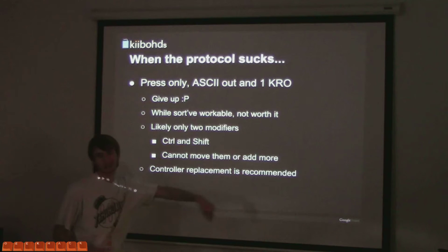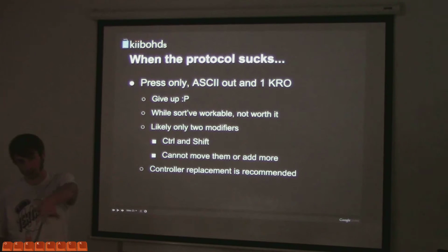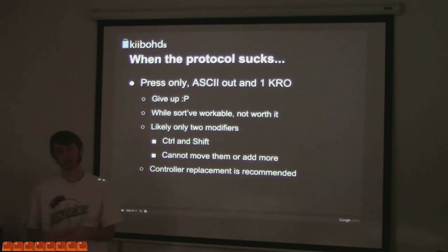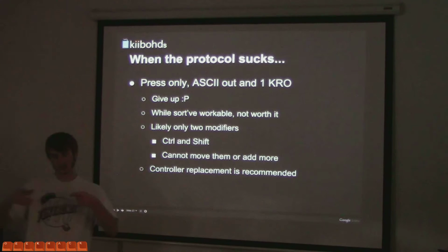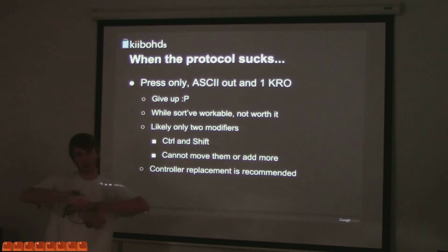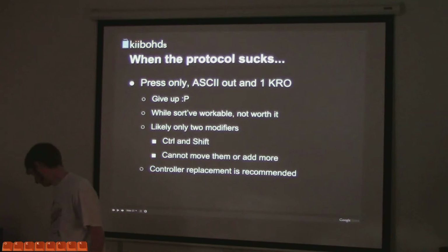You cut off the PCB and do the traces directly to the switches, or you can pull out the big microchip, and you can sometimes put something like a Teensy down if you solder the wires correctly. And then it becomes a different kind of reverse engineering exercise, just to see how it's scanning and where the pins are. Technically, it's actually kind of simpler. It's more difficult figuring out what it does.